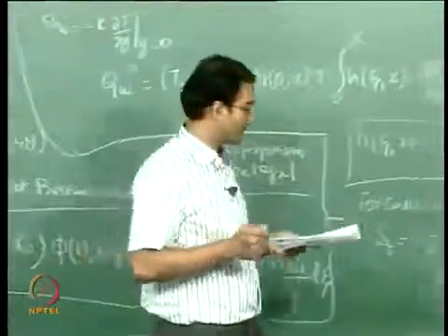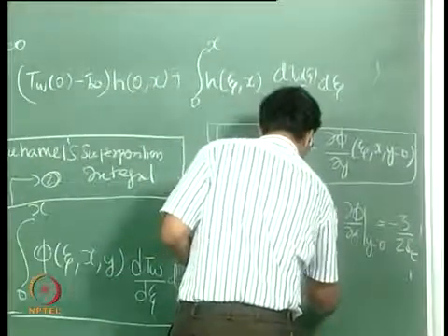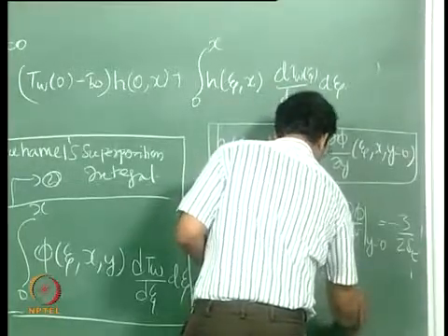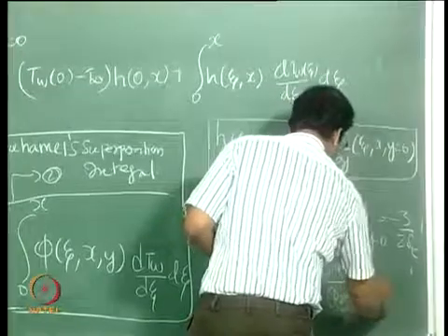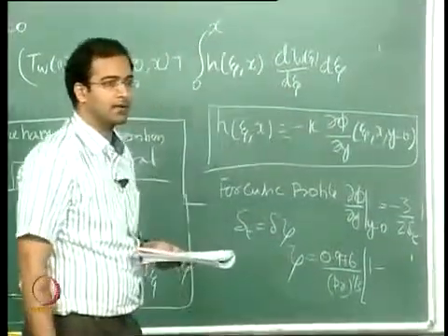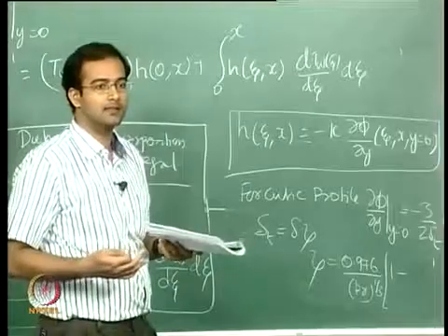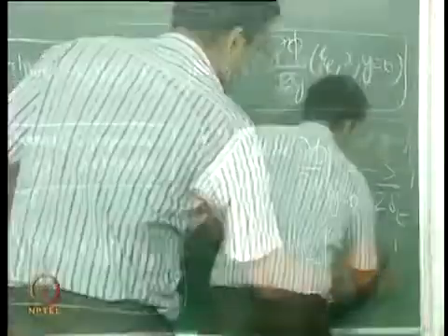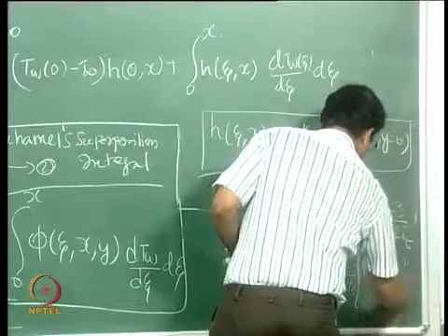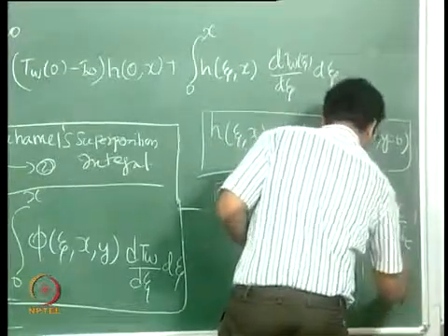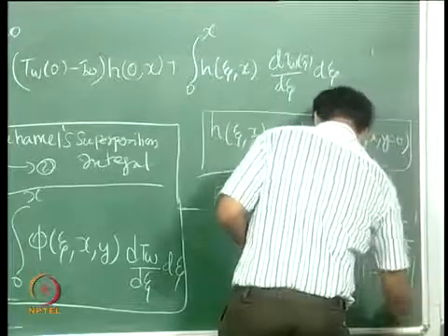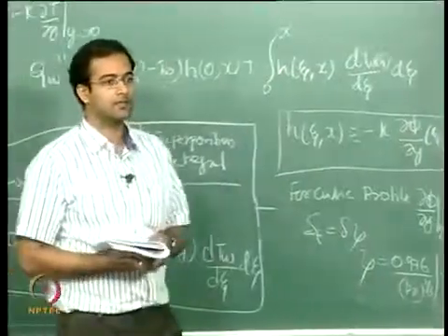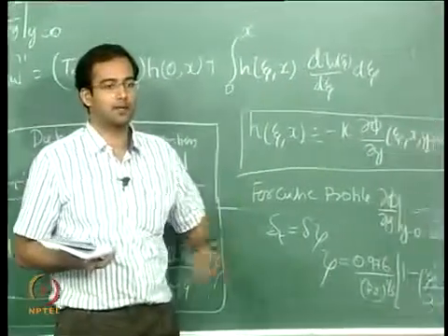length. Okay, so that comes out as 0.976 by Prandtl number to the power 1/3 times 1 minus, so the unheated starting length there was assumed as x naught. In any generic case where you know the location of the unheated starting length, you can replace that x naught by the zeta here, the whole power 3 by 4, the entire thing raised to the power 1/3, right. So this was what we derived for flat plate with unheated starting length.